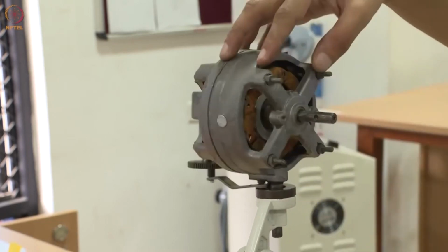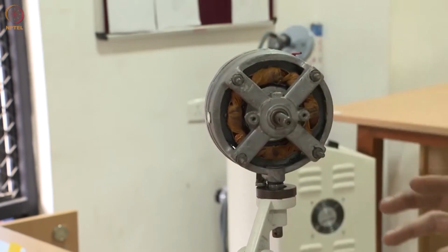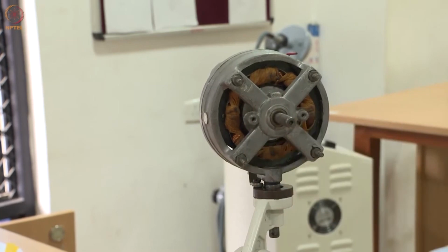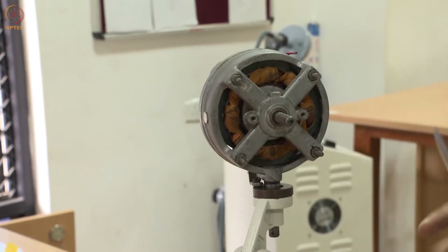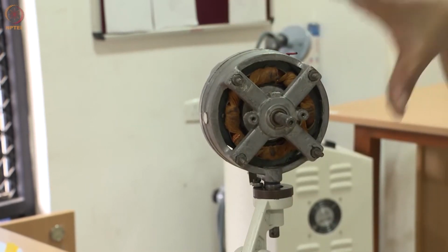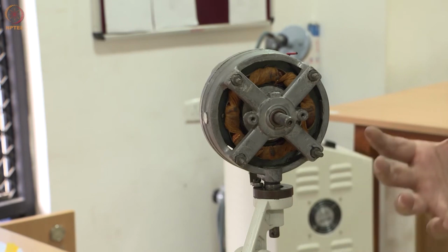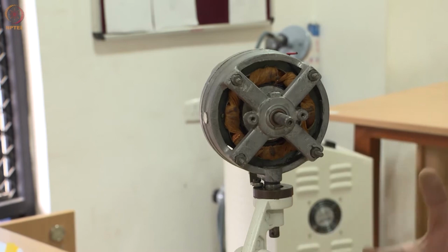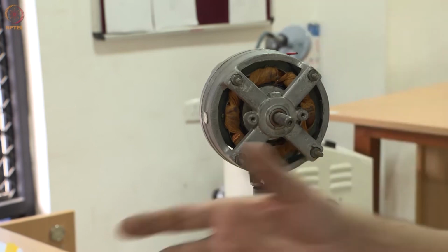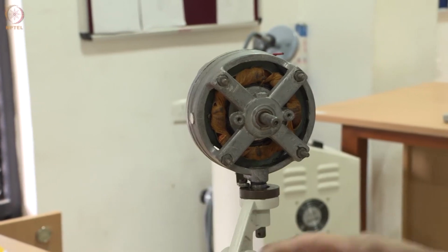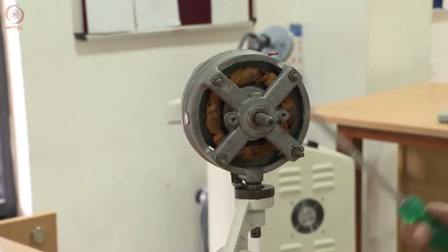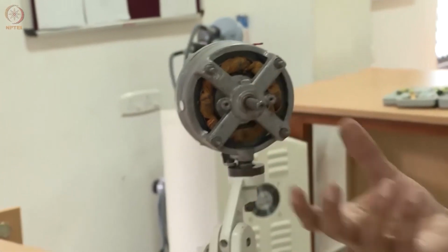So typically, if you see the fan's motor, these motors do not produce very large torque because of the way they are constructed. They do not produce very large torque because the application here is just to move air. The motor runs at a reasonably good speed, but the torque that the motor gives is very limited. So this is a feature of all induction motors. If you look at an electric drill, for instance, there the application is you need a large torque to basically drill a wall, etc. But in this case, the torque requirement is not so high.